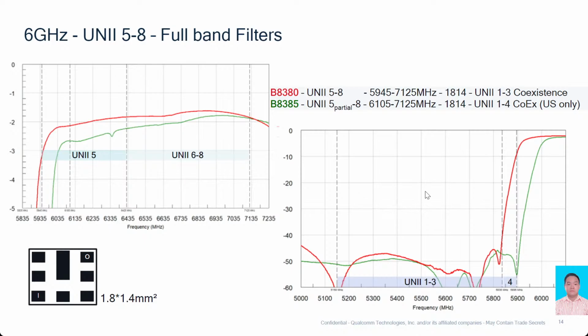On the right side, so far, not much to worry about, so we let that roll off a lot slower so far. You never know what's going to happen in the 7 gigahertz area. Right now, it's not a concern, so we're able to focus on insertion loss and very high rejection on the low side of the 6 gigahertz.